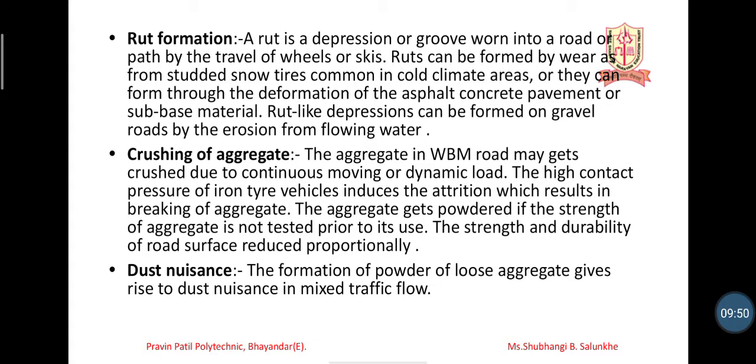Not only that, if we are not crushing aggregate properly, or if we are not testing aggregate properly for strength and everything, obviously the aggregate will lose its strength. Or if we are not crushing aggregate properly, the aggregate will also crush out because of the vehicular load, and its strength and durability will get reduced.